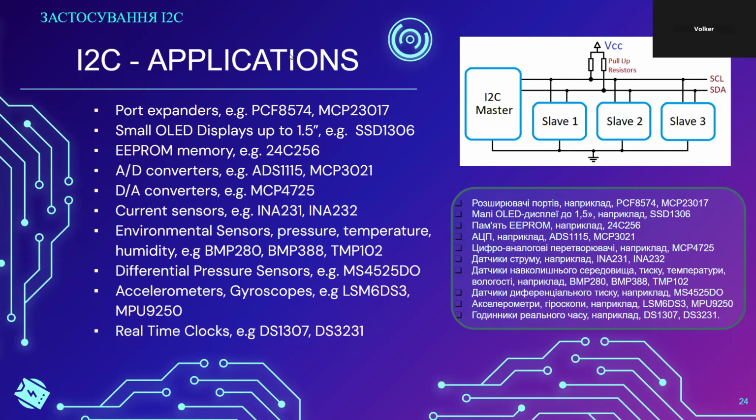So you could have an I2C interface to connect to a real-time clock, use a UART to connect to a GPS module, get a very accurate time from the GPS module, and set the real-time clock with it.